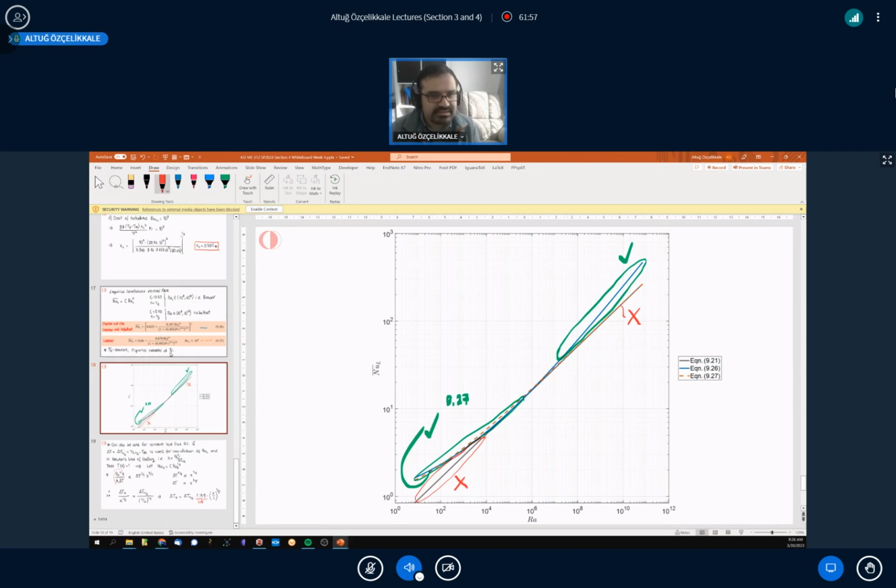Actually, we are saying that this Rayleigh number 10 to the power 9 is turbulence, but there's a transition region as well, just like with the internal flow where we said that Reynolds number of 2300 is the limit, but then the fully turbulent flow is at Reynolds number of 10,000. Similarly here, we are going to have a range where the laminar solution is going to gradually become inaccurate. So you can see that deviation between the blue line and the gray line, and that's exactly why.